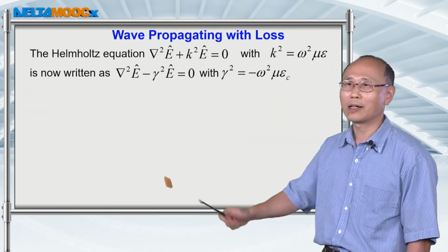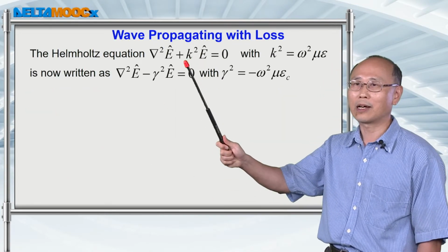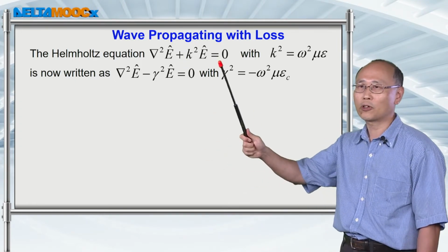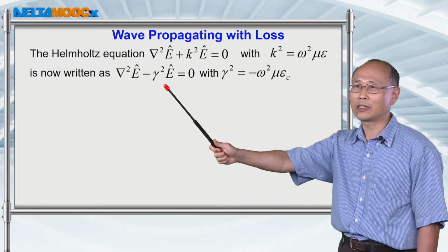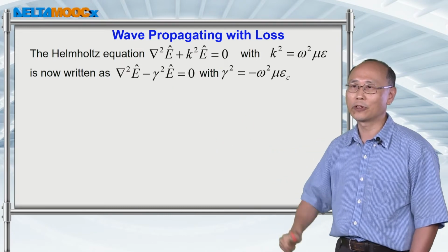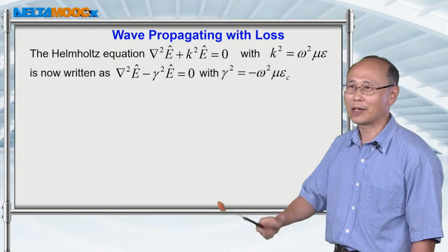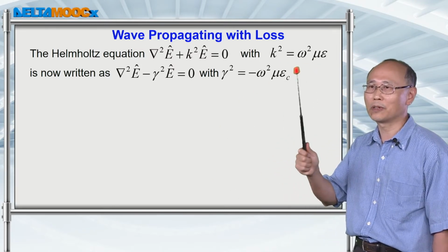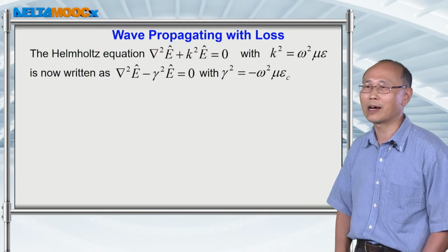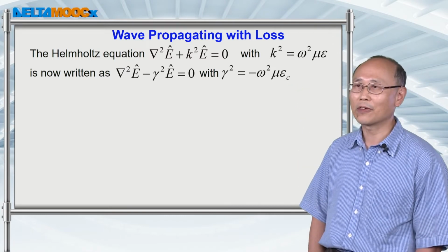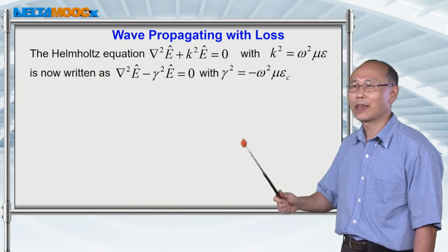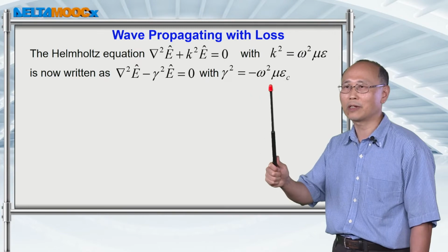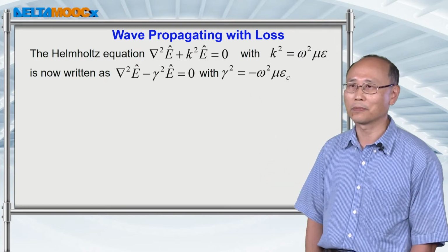So let's write this Helmholtz equation without attenuation and then convert it into the expression that we already used for the transmission line, because you have to replace this real number by this complex number defined through the dielectric material. With this definition, you have gamma squared equal to minus omega squared multiplied by mu epsilon.